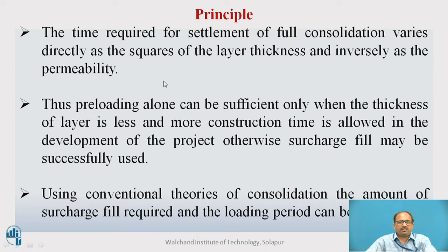This consolidation time varies directly as the square of the layer thickness, and inversely as the permeability of the soil sample. Thus, preloading alone can be sufficient only when the thickness of the layer is small. For example, if the depth of the foundation is more than 10 meters, it is not possible to apply the preloading technique here.